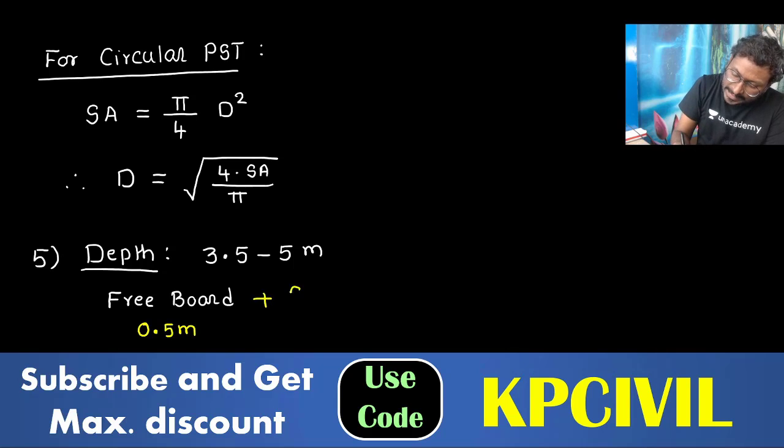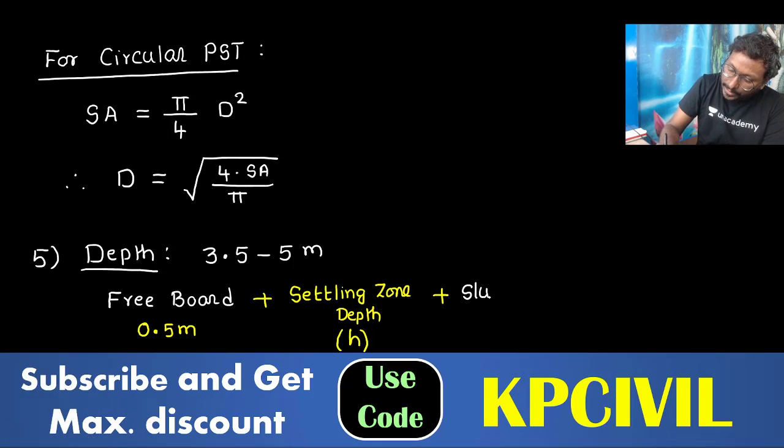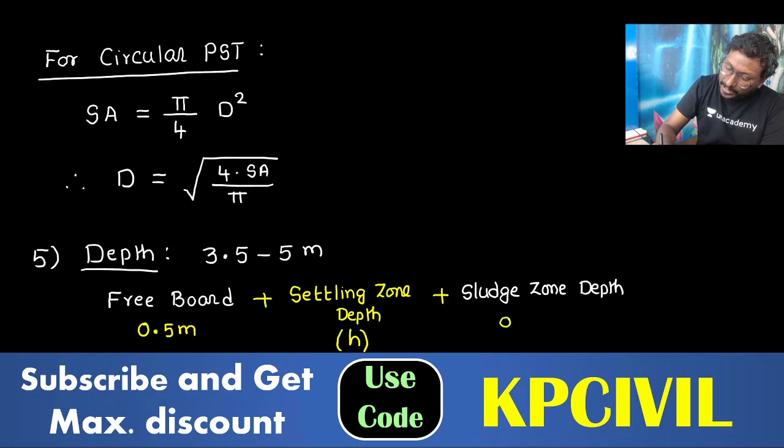Then settling zone depth or water depth, which is considered as a small h, plus sludge zone depth. The particles and impurities settle and rest in the sludge zone. Sludge zone depth is considered between 0.8 to 1.2 meter.